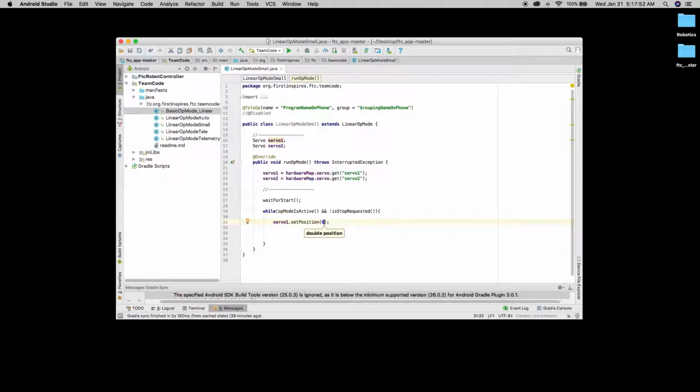Since it's a regular servo, it can go 180 degrees back and forth from its initial position and then back again. So 0 is one of those ends, depending on how you have your servo started. 1 is another one of those ends, depending on how you have it turned. When you initialize it, it'll go to one of those ends, and it'll be consistent with that. Now, 0.5, that's the middle. But you can also go in between, with 0.6 and everything.